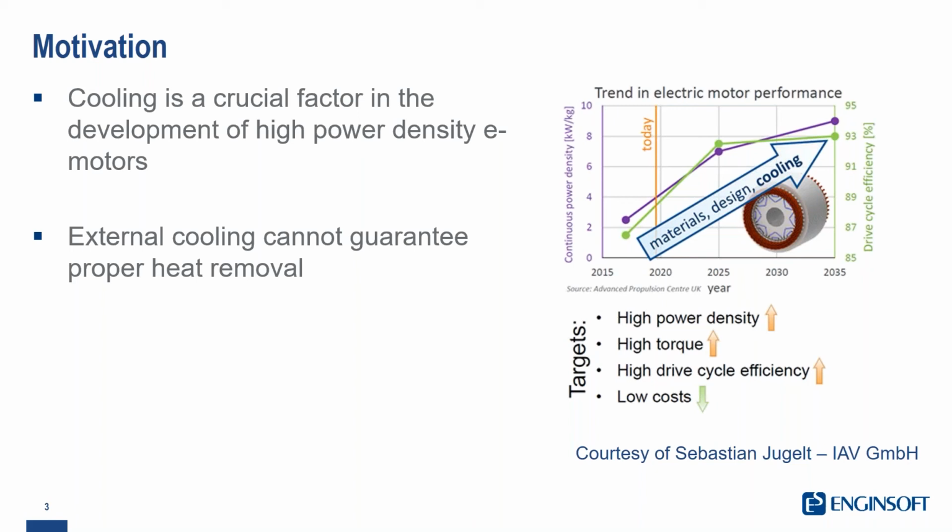And the reason is quite simple to understand. The power is generated and has to be dissipated at the center of the e-drive, while the coolant flow is on the external side. So the cooling efficiency cannot be high. So the best way to remove the heat is to bring the coolant into the area where the power is generated, and this is the core of the e-drive.